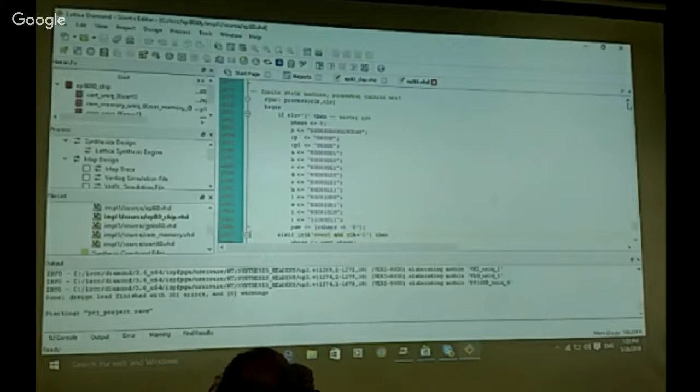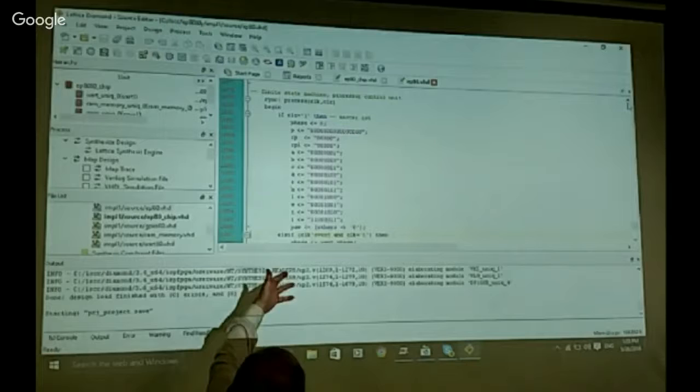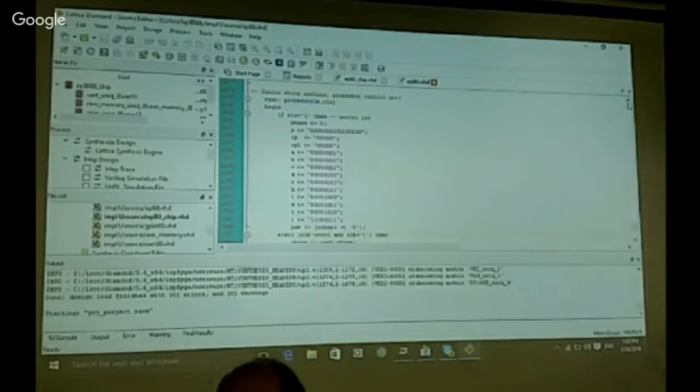Okay, and all the other registers, you can initialize them any way you want. You can put in any pattern in the registers, because most of these registers get changed when the program is running, but it's nice to have some initial data there to help debugging. So you know that I have this register on the reset, and if it got changed, it has to be changed the right way.